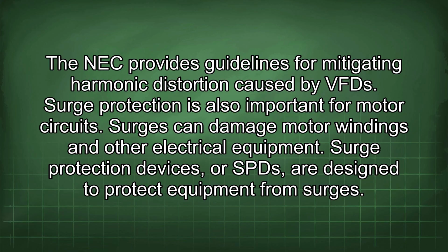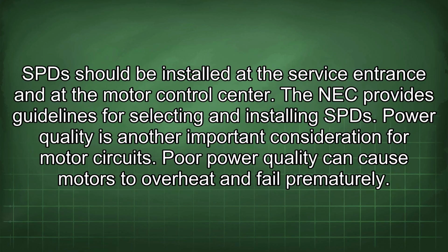Surge protection is also important for motor circuits. Surges can damage motor windings and other electrical equipment. Surge protection devices, or SPDs, are designed to protect equipment from surges. SPDs should be installed at the service entrance and at the motor control center. The NEC provides guidelines for selecting and installing SPDs.